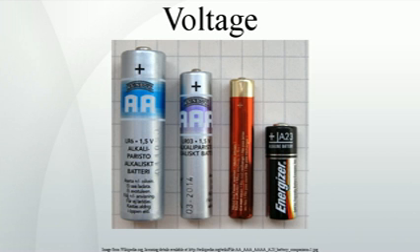Addition of voltages. The voltage between A and C is the sum of the voltage between A and B and the voltage between B and C. The various voltages in a circuit can be computed using Kirchhoff's circuit laws. When talking about alternating current, AC, there is a difference between instantaneous voltage and average voltage. Instantaneous voltages can be added for direct current, DC, and AC, but average voltages can be meaningfully added only when they apply to signals that all have the same frequency and phase.